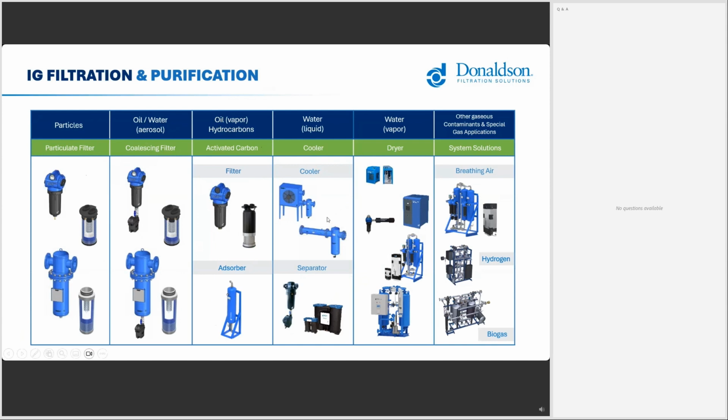But when doing that, you have to take care to have a separator installed downstream of the cooling system in order to remove the bulk water which is coming from the condensed water vapor in this aftercooling system. And if the condensate contains not only water but also residual oil, then you also have to apply oil water separators in order to separate your condensate.